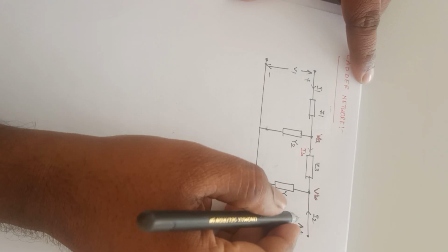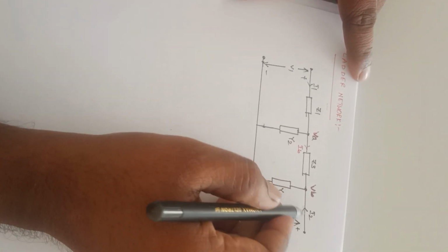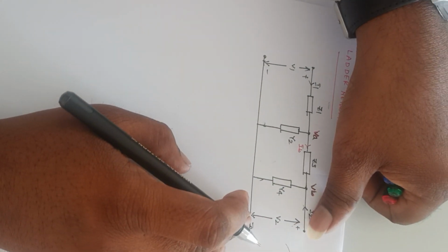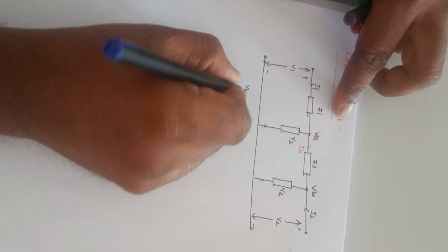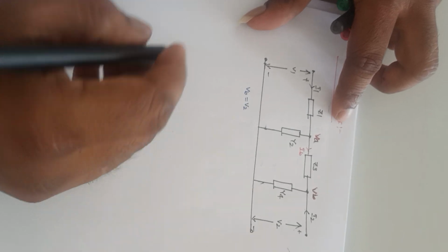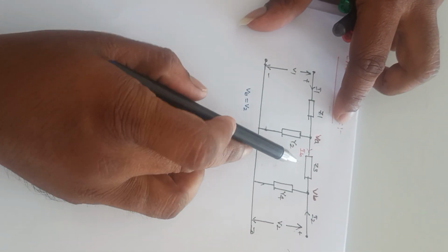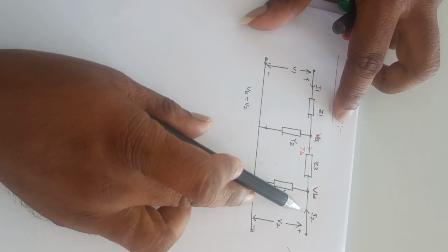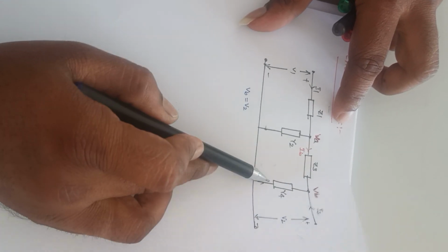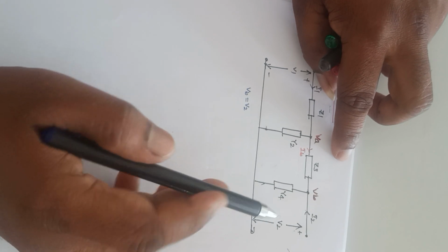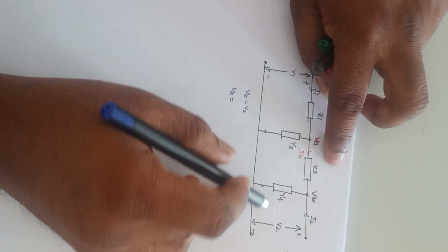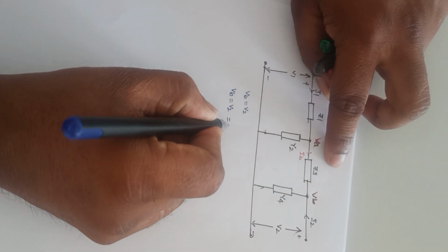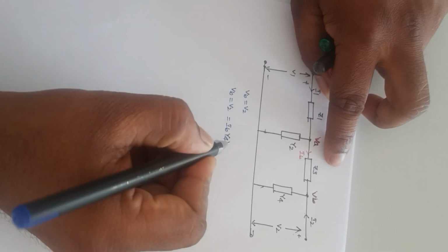So for this, you see, since this V2 is 0, I2 is 0 here because it is open circuited. This voltage VB is equal to V2. That is the first thing. Next, this current IB will flow like this. Because I2 is equal to 0 here, this current will flow like this. So this VB is equal to V2, which is equal to IB into Y4.